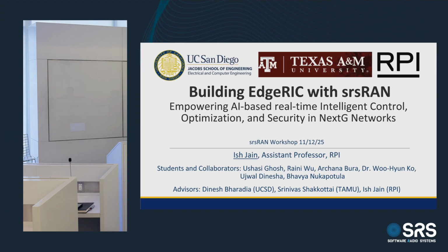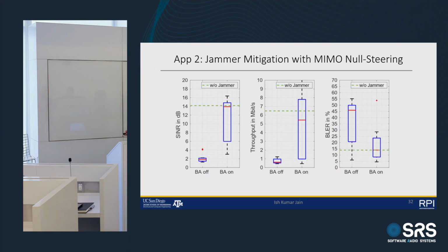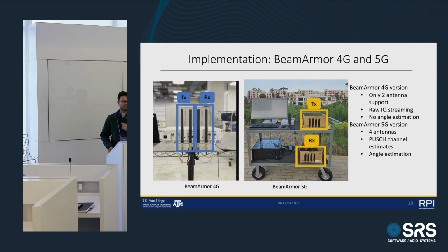So there could be some artifacts from the antennas. If you have seen the setup, we use antennas λ/2 apart, which helped us remove any coupling between antennas or any extra delays from the antennas. But some hardware artifacts could be there. Despite them, the beamforming vector is independent. It applies to the antennas as long as they are λ/2 separated.